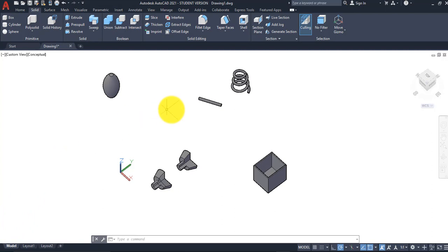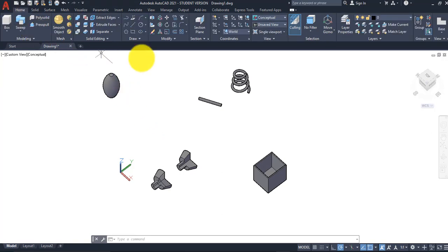We said in class that we would create a layer called viewport so that we can create these openings in the layout space. So we'll go to the home tab at the top left, and go to layer properties here.